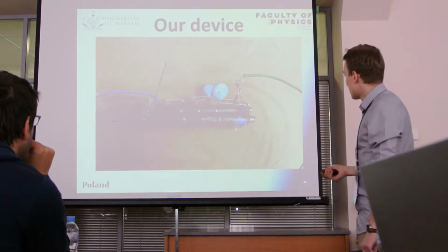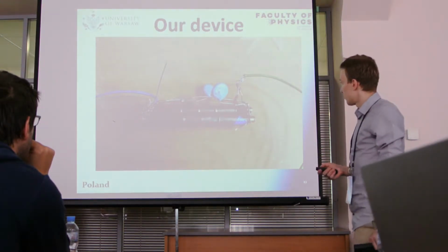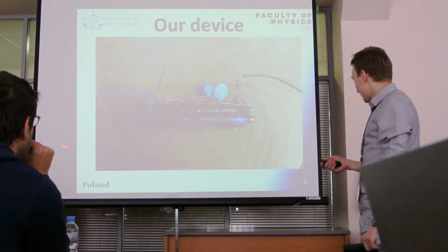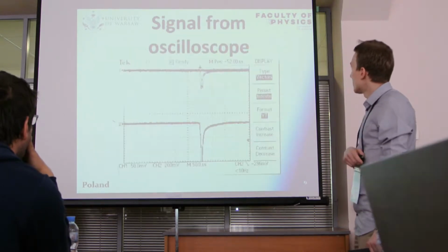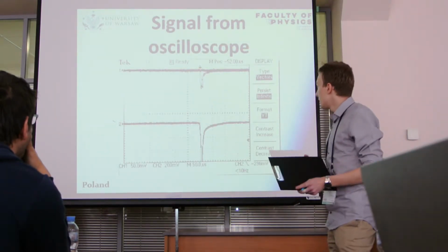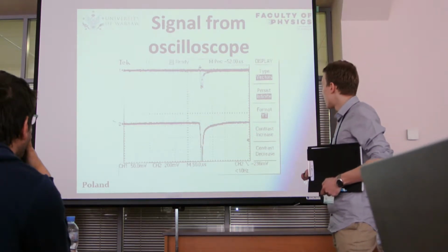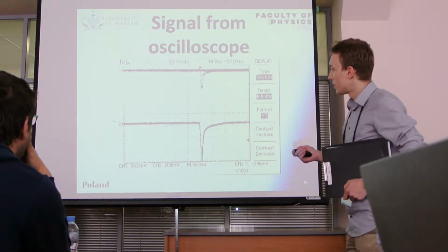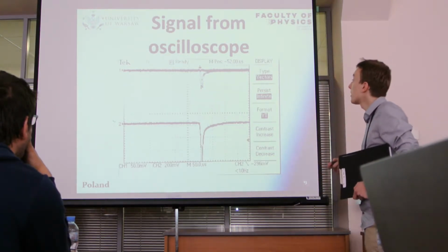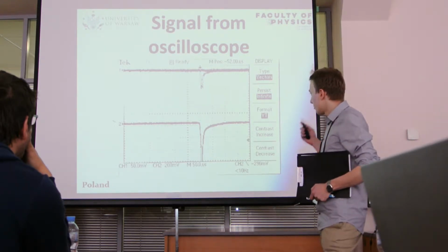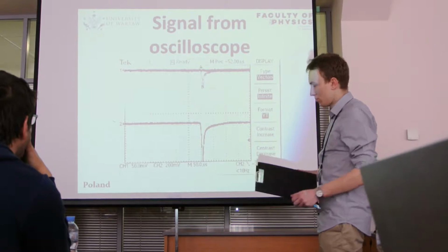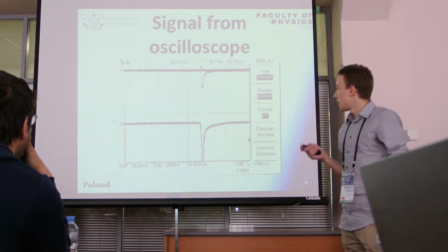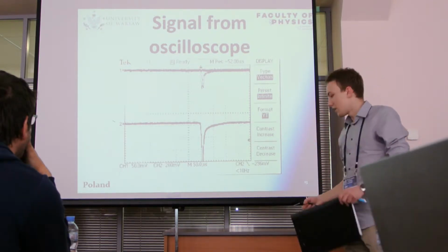So our device looks like that. There is no plate in this photo because the final photo sadly was corrupted. As you can see, it is a very simple circuit. Now we plug it into an oscilloscope and we put it in a trigger mode for one of the channels, for the Geiger tube whose response was higher, and all we have done to obtain our measurements was only to calculate the number of events per time.